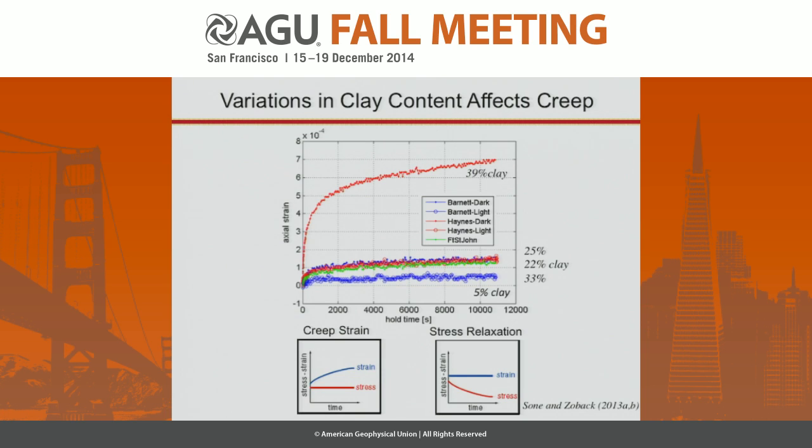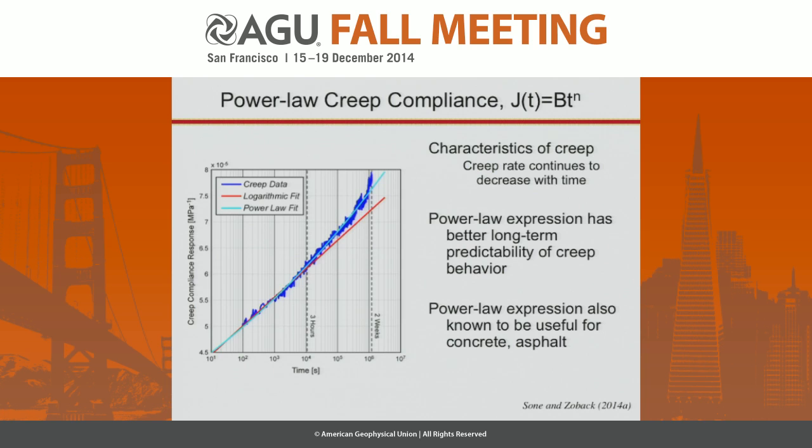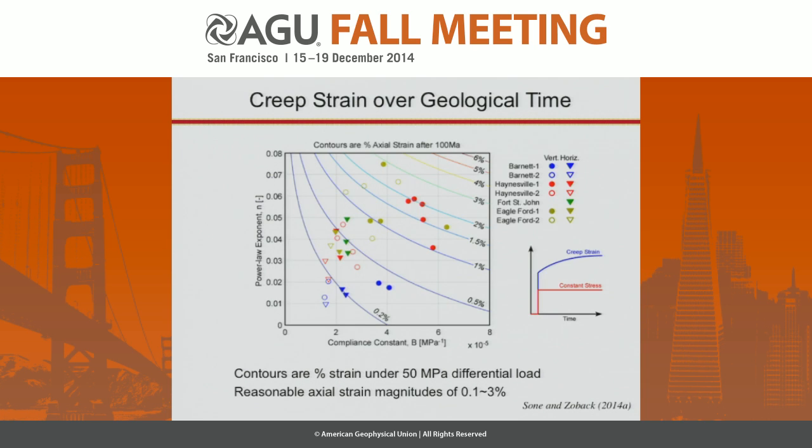Now, the interesting thing about creep is that, under this kind of loading condition, it creeps as a function of time. Under this kind of loading condition, where we hold the strain constant, the stresses relax as a function of time. So we've developed a constitutive law. Since it's all published, I'm going to run through it and just give you the general points.